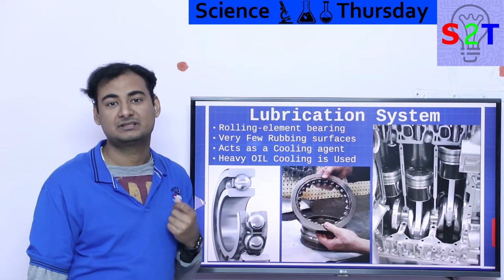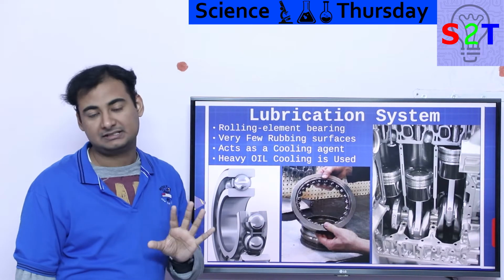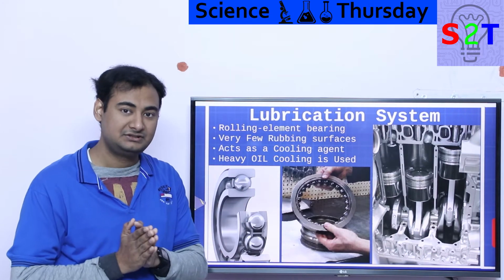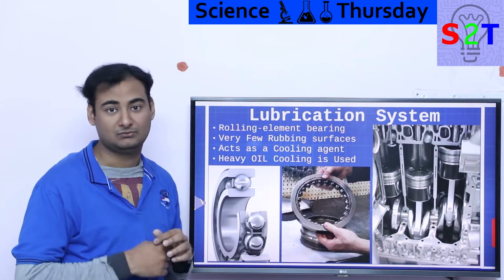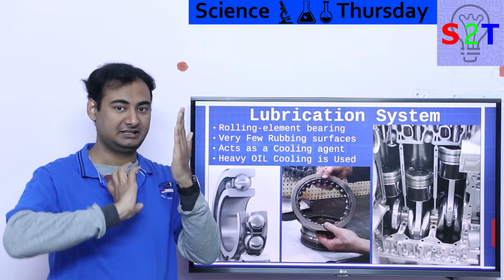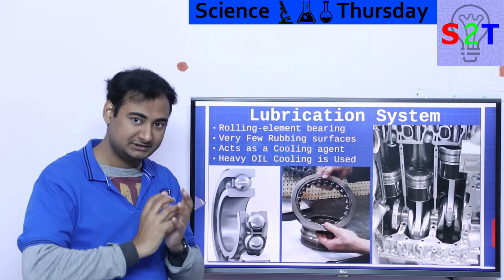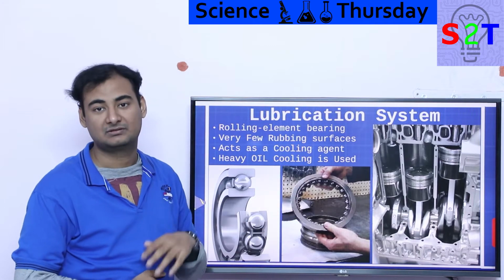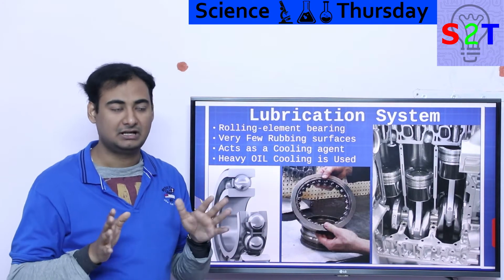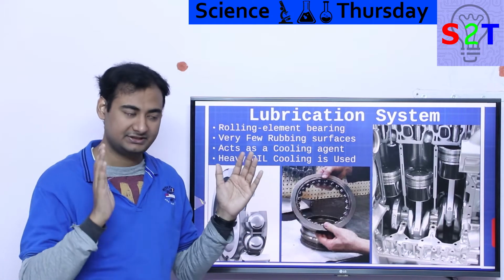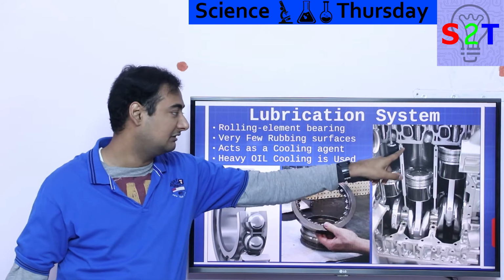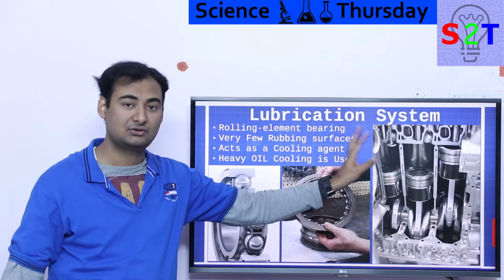Well, a jet engine employs something very unique. Unless it is something very cheap, most places in a jet engine employ roller bearings. Why does that matter? Simply because there is no sliding contact. Nothing is sliding, everything is rolling. By employing these very expensive roller bearings, I have provided a video down below, they reduce the friction to almost negligible. Again, it's not zero, it's just reduced drastically. Instead of metal on metal contact from crankshaft to cylinder wall and all that, it's almost all gone.